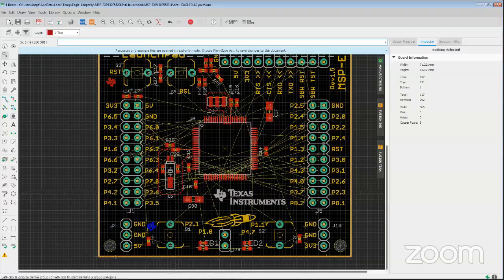The reason for that is that the autorouter will not modify anything that's already routed at the time that it starts to run. In other words, if you do all the important traces manually first, when you run the autorouter it is not going to touch anything that you routed manually. It's going to leave it alone, exactly as you left it.